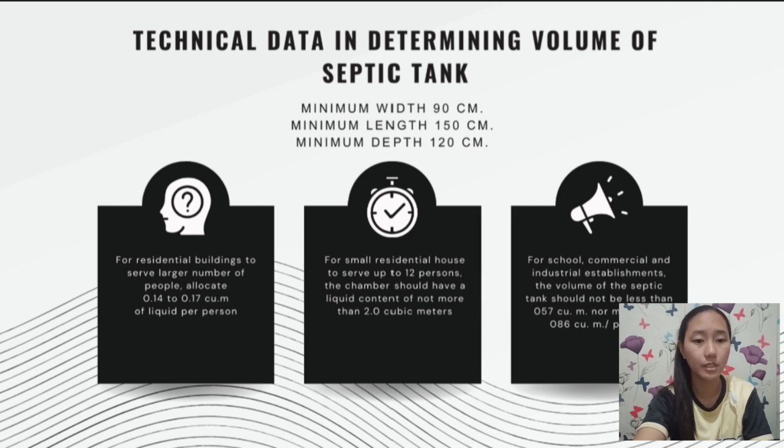When large amount of water waste is coming from the shower bath, laundry, and others, it is not advisable to permit these waters into the septic tank. Likewise, all downspouts collecting water from the roof should not be allowed to terminate into the septic tank. Rainwater should be conveyed to the storm drain.